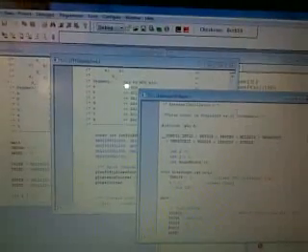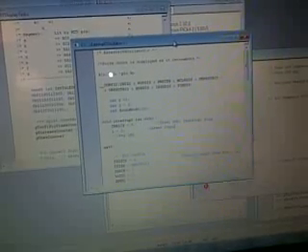The next one is external oscillator, which I used to get the timer counting from an external clock source, which in this case is the pulses from the rotary encoder. That took some getting used to. Once I got that, I got it to count and display the number that it was getting from the rotary encoder. It would just continually display it in a big loop.